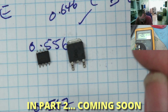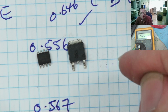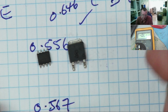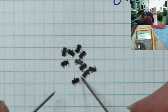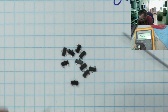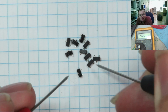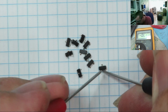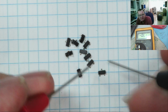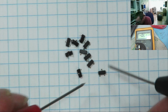But just before we do that, I want to show you how to test transistors out of circuit, the surface mount ones, because this is where you can become quite confused. Here we have some very common NPN surface mount transistors. This is 1AM as the SMD code. It's very common. And we can see with these type of transistors that this pin, the one that is now stuck to my probe, is almost always the base or the gate. This could be a bipolar transistor in this package. It could be a MOSFET. Let's have a look at it.